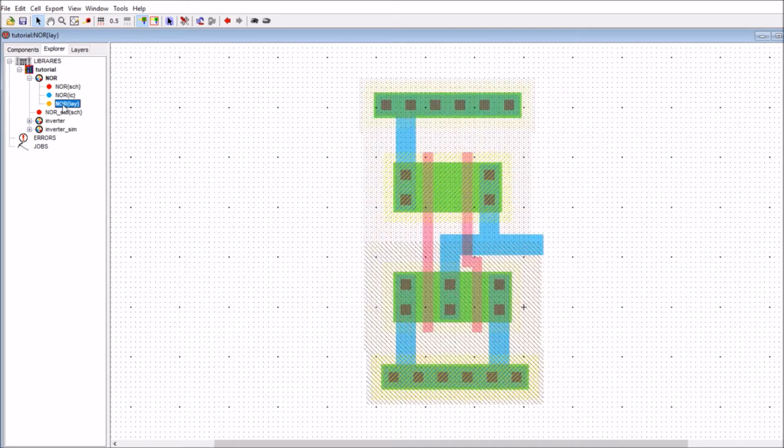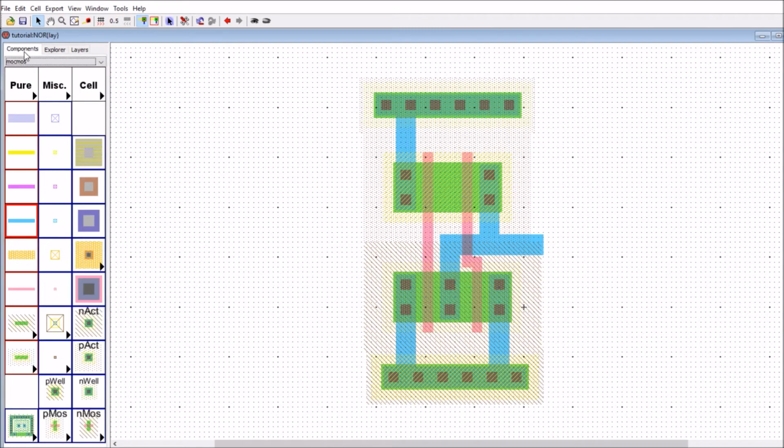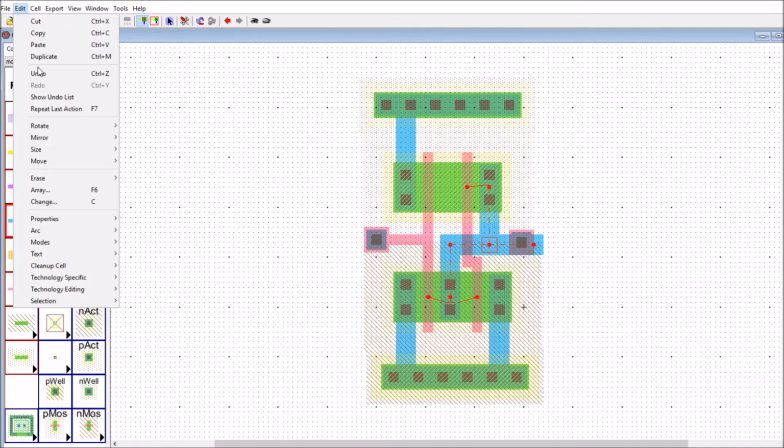So head into the layout and we're going to have to get access to this layer here. So how do we get access to that layer? Well, we've got to use this via here. So we connect in here, left click, right click, and that's this connection. And again, we can grab this one here and grab one of these. We can head over here, and at this level, we're going to have this one here heading into there. So left click, and undo that, edit, undo.